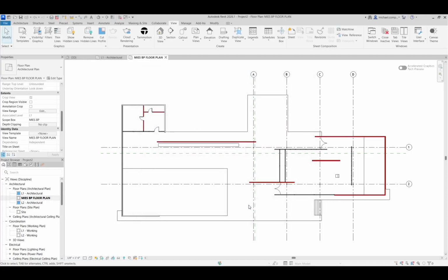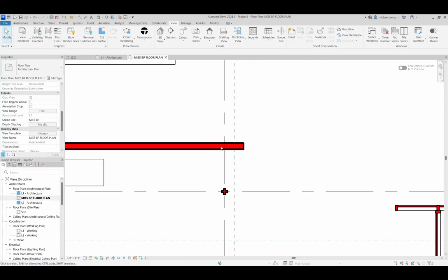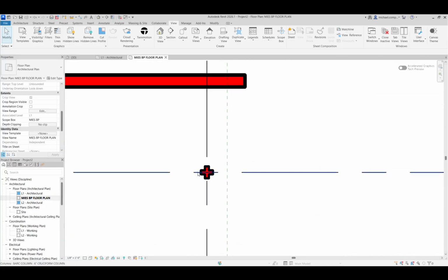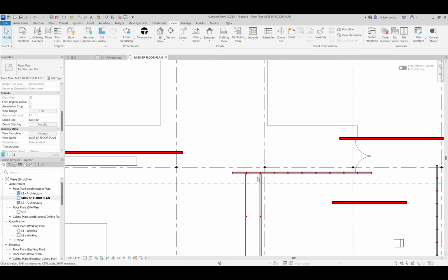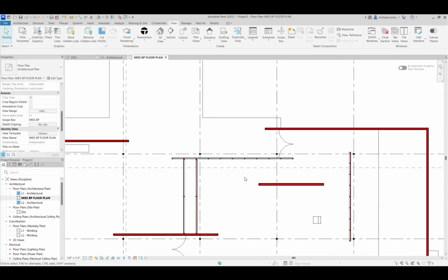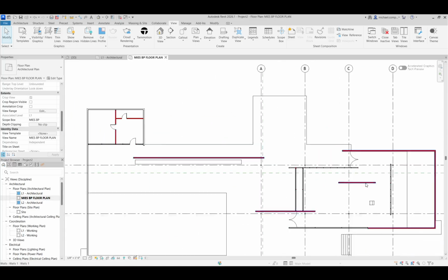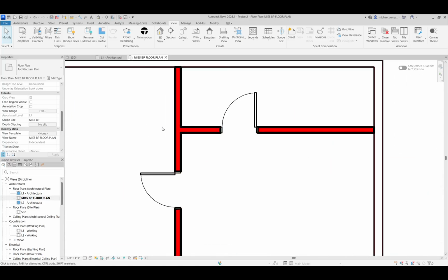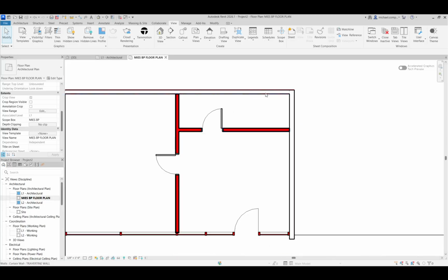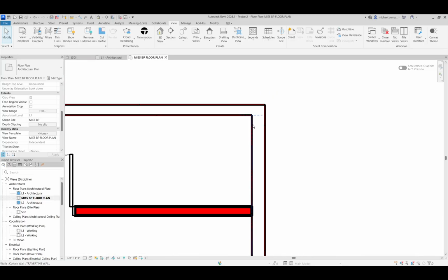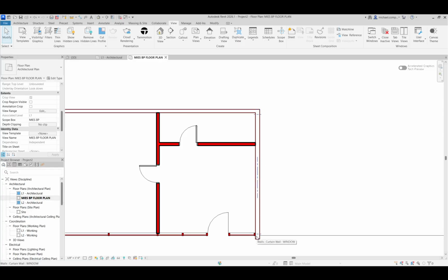Now, everything that is a solid object, or everything that is being cut through, is highlighted in red, right? So that's being highlighted in red. The cruciform cross shapes that we saw, the mullions in the curtain walls, the freeform model walls that we did, the regular walls that we did, the Revit walls. And then you're probably like, well, wait a minute. These walls aren't pocheted. That's because they're not walls by definition.